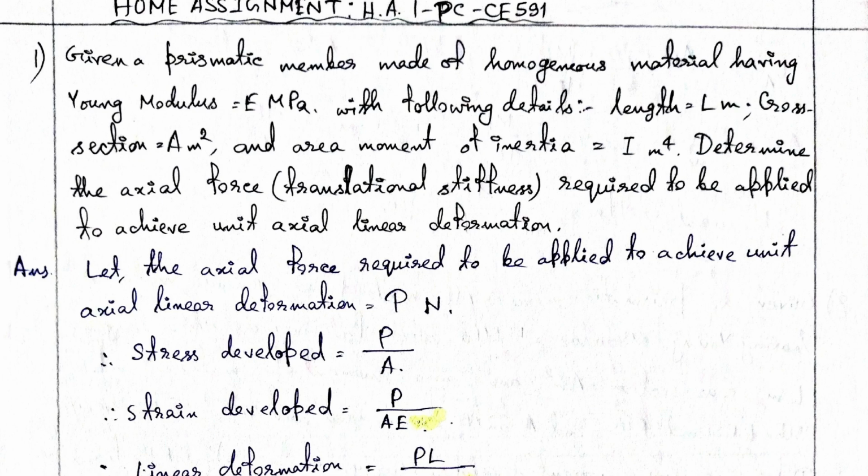That is, here we don't convert Newton per mm square to meter or Newton per meter square. But if we have a problem where Young modulus is 2 into 10 to the power 5 MPa and length is 1 meter, then we can convert the Young modulus into Newton per meter square, or we can take the length in mm.